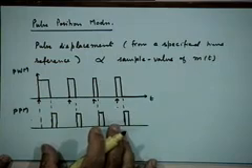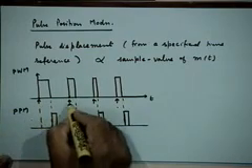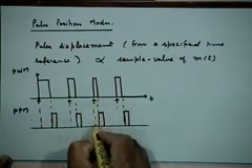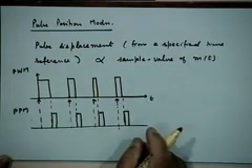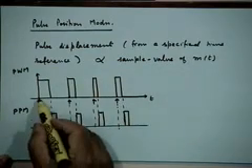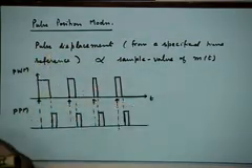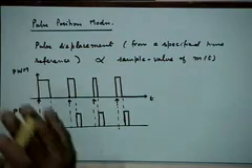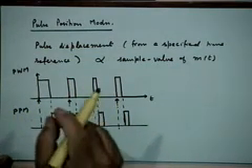Suppose you have information about where my pulse is starting. Yes, this is the information about the pulse starting. If you differentiate, you'll get two pulses: a positive edge and a negative edge. What do you do with that? Remove the positive edge, and then you have a negative edge, and that has to be converted into a positive pulse of this kind somehow.